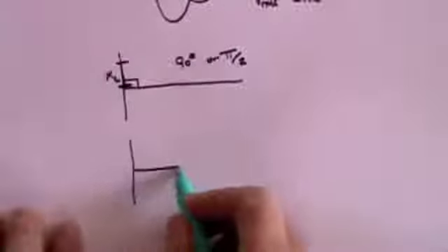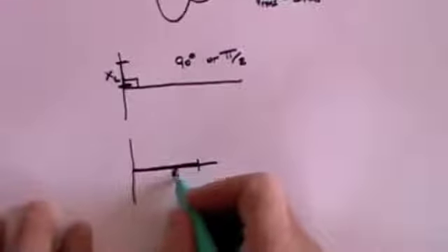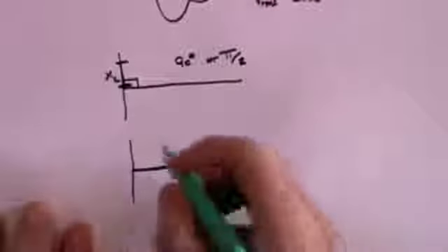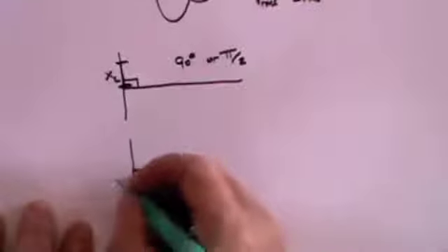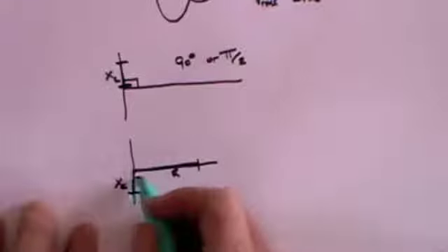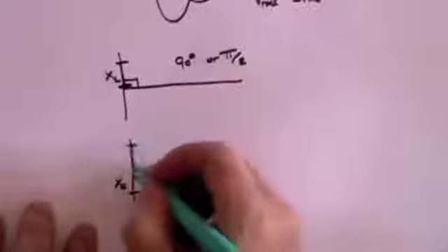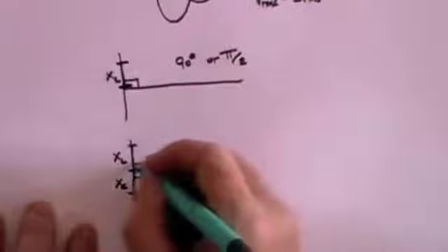So just to recap on the phasor diagrams, if you're drawing a resistance, it will be R in this direction with a phase angle of 0. If you're drawing a capacitance, then the reactance value is the length of that line and the angle is at minus 90 degrees. And if you're drawing an inductance, then the reactance effect is the length of that line with an angle of plus π/2.